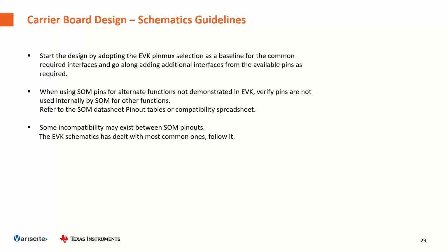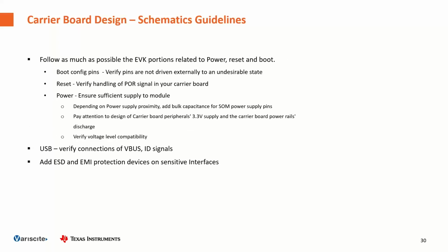Let's say that when designing the board, you need to manage some specific points. First of all, the boot configuration pins. This SoC is able to boot both from the MMC and the SD card. We manage the boot device through a switch on the board, but the customer may want to customize the carrier according to his needs, as I said. In any case, you have to manage these boot configuration pins.